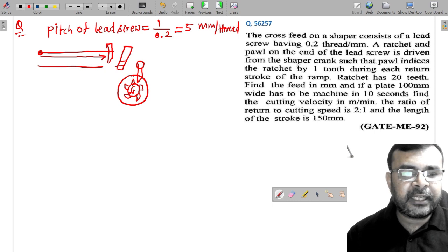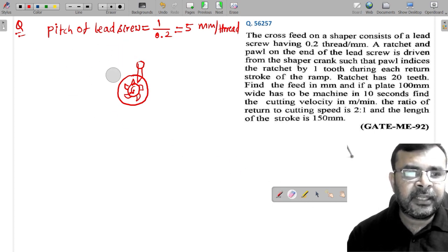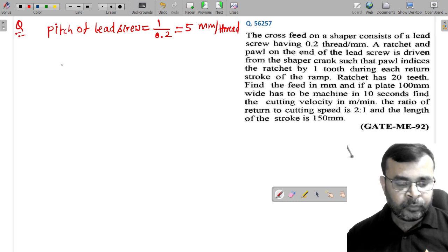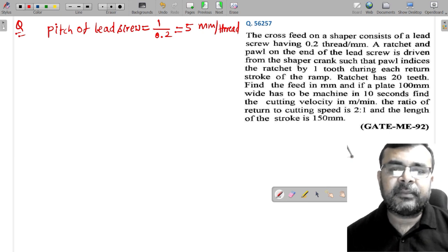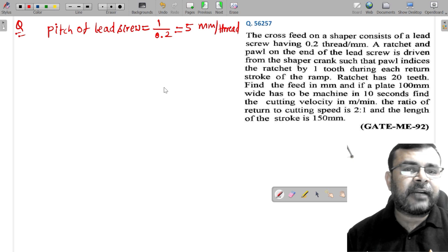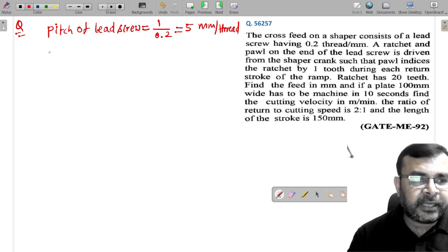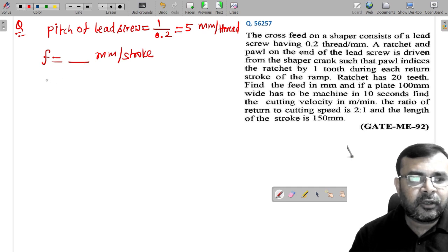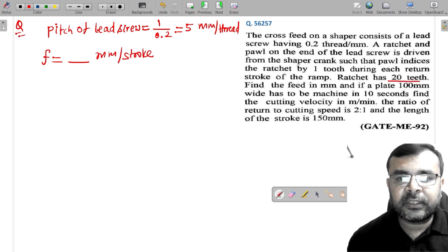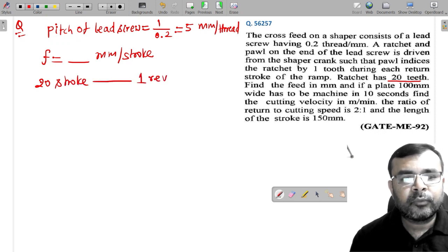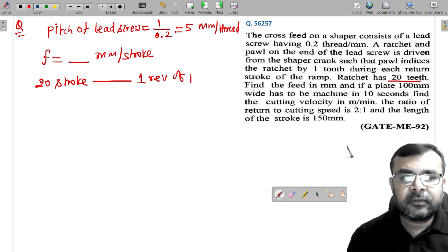तो ऐसे करके अगर हम देखें तो एक कंप्लीट रोटेशन ऑफ रैचेट पावल, यहाँ पे हमें क्या मिल रहा है 20 फीड, मतलब एक बार जब रोटेट होगा तो आपको 20 डबल स्ट्रोक मिलने वाले। इज इट राइट? एक्चुअली हियर आई एम इंटरेस्टिंग फॉर डिटरमाइनिंग द एडवांसमेंट फीड, एक्चुअली फीड और यू कैन से द एडवांसमेंट ऑफ द वर्क पीस पर स्ट्रोक। एक स्ट्रोक में कितना एडवांसमेंट हो रहा है हमें एफ कैलकुलेट करना है। इज इट राइट? तो अगर मैं यहाँ पे एफ कैलकुलेट करूं तो मुझे किस यूनिट में चाहिए? एफ इन मिलीमीटर पर स्ट्रोक। इज इट राइट? मुझे इस वैल्यू को चाहिए। और देखो यहाँ पे 20 टूथ है। इज इट क्लियर? मीन्स 20 स्ट्रोक आपको मिलने वाले हैं इन वन रिवोल्यूशन ऑफ सिंपली यू कैन से पावल, करेक्ट?